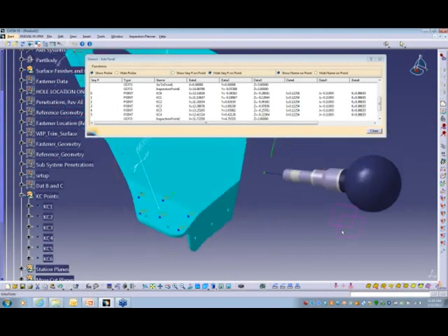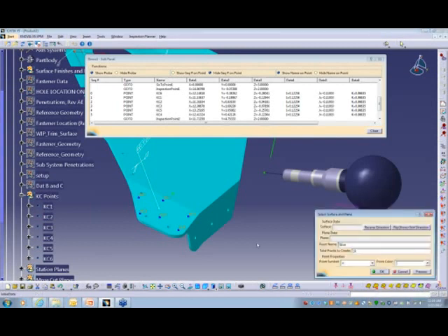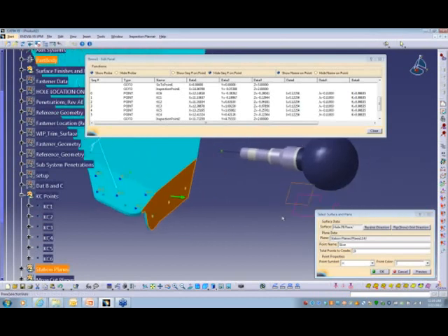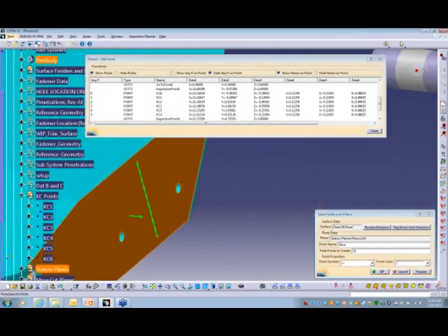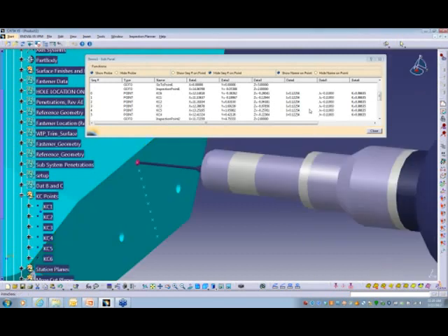And these planes right here could be section planes or station planes that the customer wants your part inspected to. So we have a tool for that. We can pick this button right here, and we can say we want to put 10 points. We can pick that surface. We want to approach it from here. We want to cut that plane. We want to say preview, and it's showing that we're going from the bottom to the top, and we can say OK.